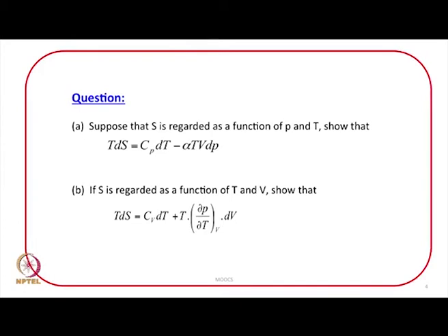So what we have discussed in this particular lecture is that the various thermodynamic properties are not just applicable to ideal systems. The difference in Cp and Cv, for example, can be expressed in many forms, and what we have to look for is to express this in a form which results in thermodynamic properties that can be experimentally determined.